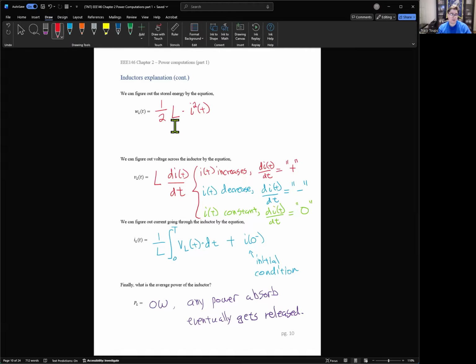Okay. So in essence of changing the current, the bigger your inductor, the bigger the L, the stronger it is to resist the change in current. So if I'm trying to push 1,000 amps and I have like a 1 microhenry inductor, it doesn't have enough energy storage to stop 1,000 amps flowing, right? It's just not going to do much. Now, if I have a 5 Henry or even a 1 Henry inductor and 100 amps, that 1 Henry is going to stop it for quite a while. Okay, we're going to feel that. So that's all L means, is just how big the energy tank is, how big the inductor is, and how much it will affect your circuit.